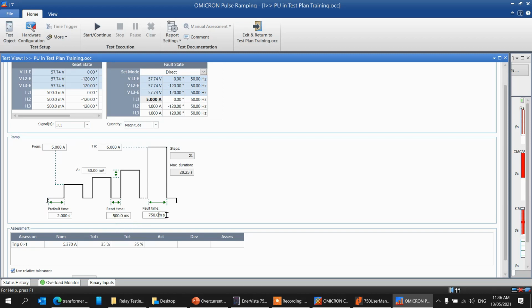And again, the reason for the hold time to be higher than the threshold time is, as Francis explained earlier, there will be a process inside the relay. That process needs to be finished first before the relay will trigger any output. And we are injecting this current on all the three phases, isn't it?